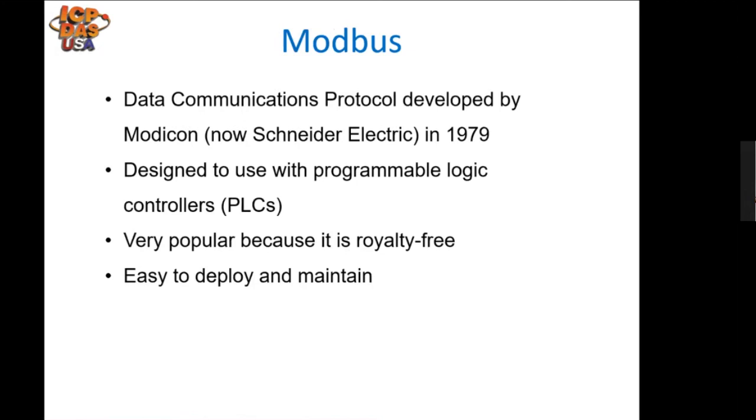Modbus is a data communication protocol originally published by Modicon, now called Schneider Electric, in 1979 for use with their programmable logic controllers, or PLC. Modbus has become a popular communication protocol and is now a commonly available means of connecting industrial electronic devices.